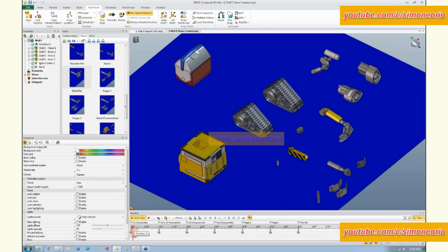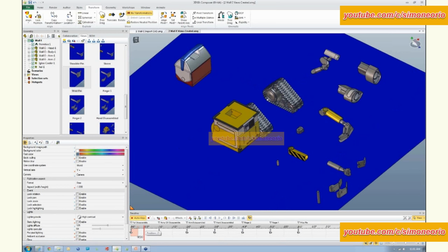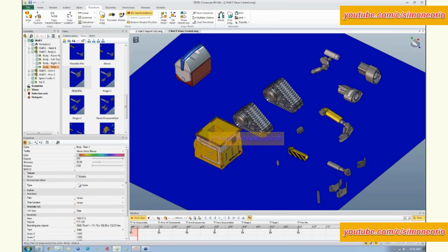So this is where our filters are going to come into play. If I take this body and move it back and forth, what I would rather have it do is come up, across, and then down in between these tracks. So I'll select the body just by clicking on it in my screen here, and I'll also select the little door that goes along with it.